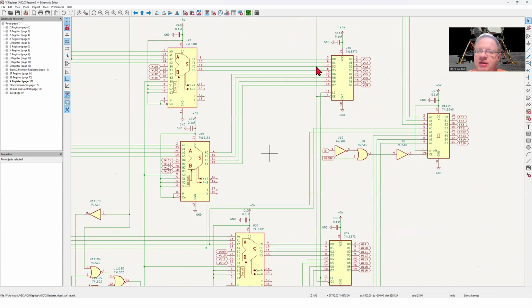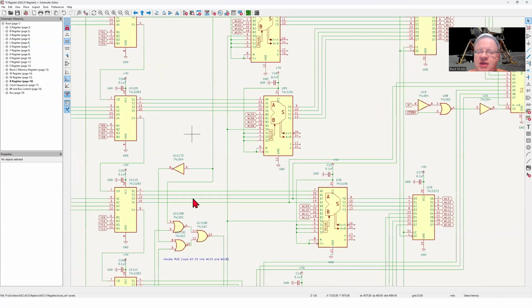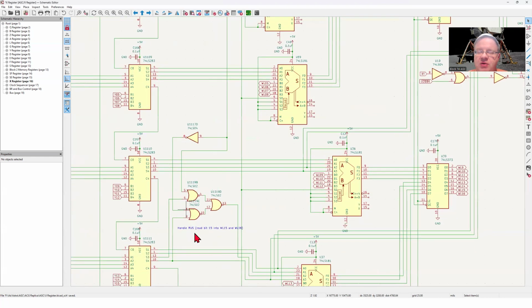And then all of that data heads out onto our latch, where we use the appropriate read timing based on the circuitry we just talked about. And then there's some logic to enable based on when we're being asked to read data out onto the write lines. Now, in the case of the X register, or the U register in this case, because it's the output of the summer, there are two additional scenarios that we have to deal with.